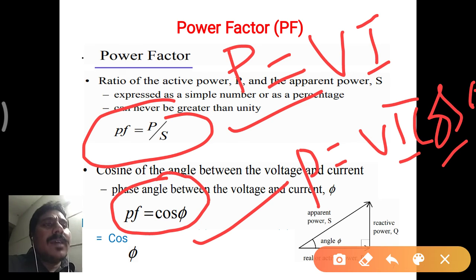Even in our college also, we are maintaining some power factor. It is better to maintain one. At least we have to maintain 0.9 in the better case. If the power factor value reduces, the total active power also reduces. So in that way, power factor is a very important one.